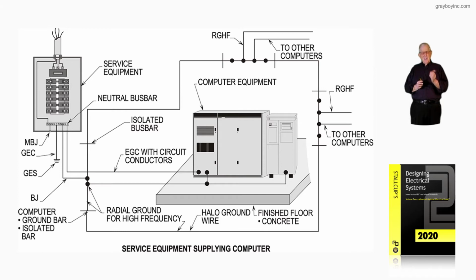But what we're saying right above the figure loop, that you either cord and plug connect in accordance with 250.146(D) and the informational note, or 250.96(B) as in boy informational note where you hardwire.